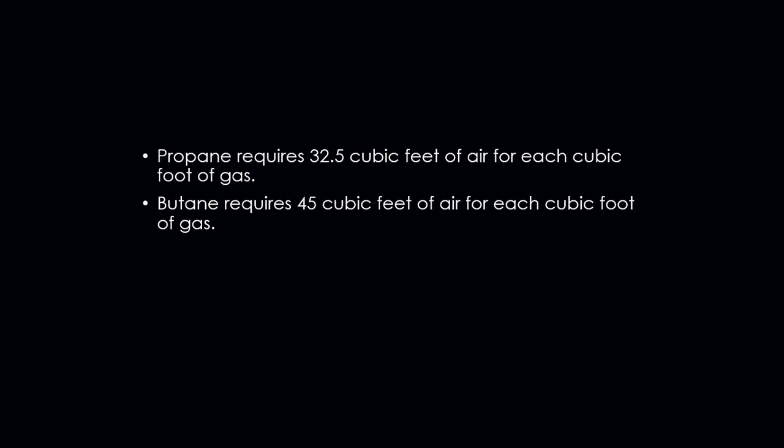Now, natural gas has a smaller specific gravity than air, so it's not going to need as much air as butane and propane would need. We would need to take that into account to make sure that we are burning all of the elements inside each one of these gases in order to achieve complete combustion.